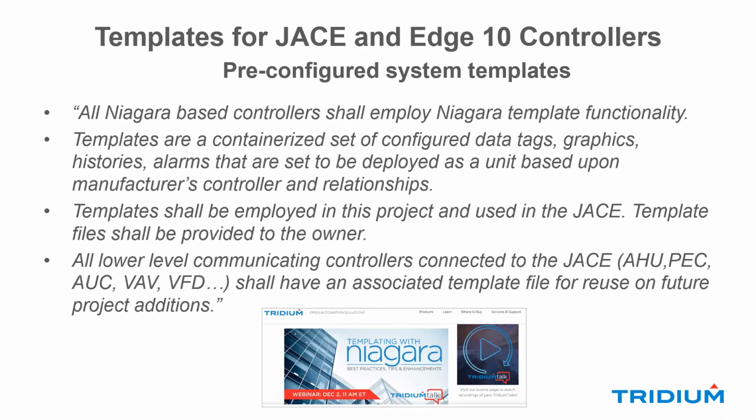They're extremely powerful, and they'll save you a ton of time later. It can be by brand. You can say, here's a template for the Johnson VAV controller, a template for the Honeywell controller, a template for the KMC controller. So the whole idea is building these standard libraries for future use.